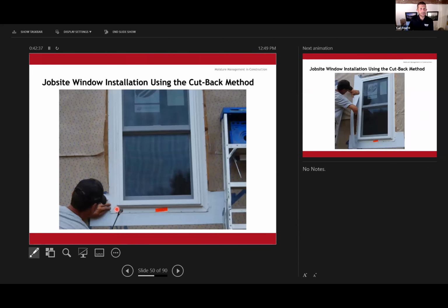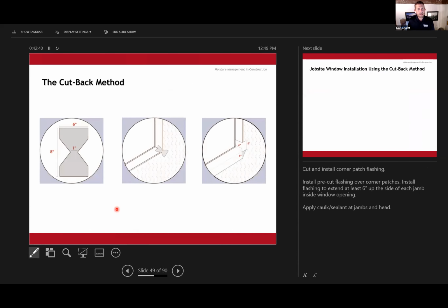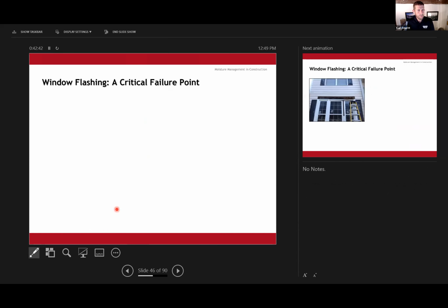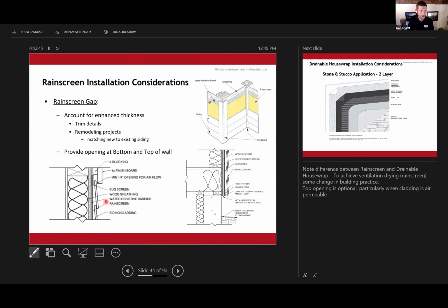So let's take a closer look at that here. And this is something, Justine, that we could take on a project by project basis and look at a little more specifically. But here you've got your finish board, right? And if this is a cedar shake or a shingle, it looks like there's maybe 3/4 inch of that cedar shingle covered. On the coast, maybe you want to beef that up a little bit, just to protect it even further from those wind-driven rains. It's a good question. Thank you.